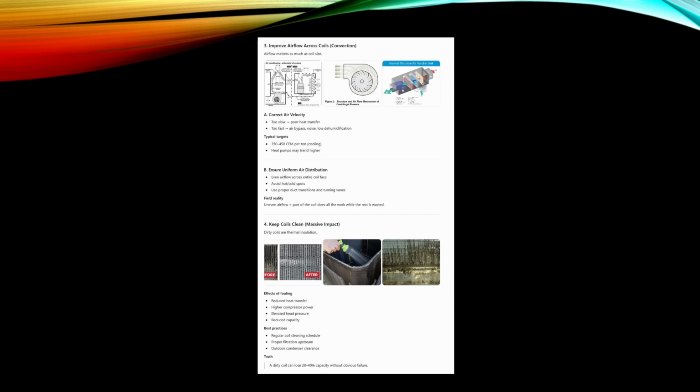Here we have one example in which we have a coil heat transfer unit in a duct. Typically in this kind of case we have a duct enlargement, and be very careful in this kind of case that you have even velocity before this coil heat transfer unit. Maybe you need some guide vanes.